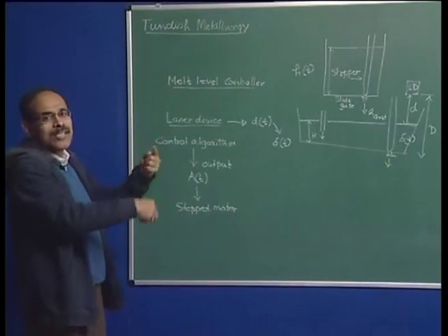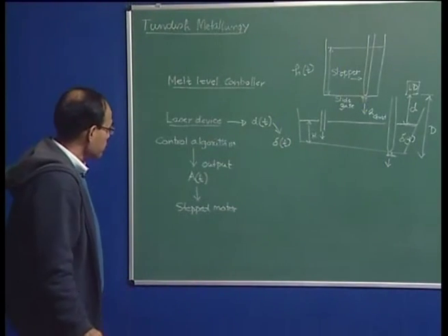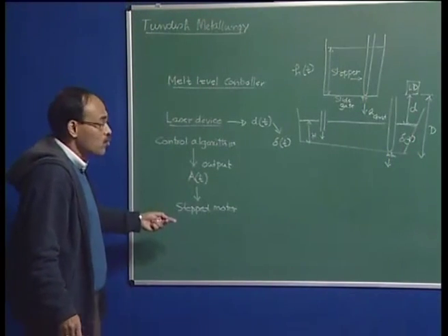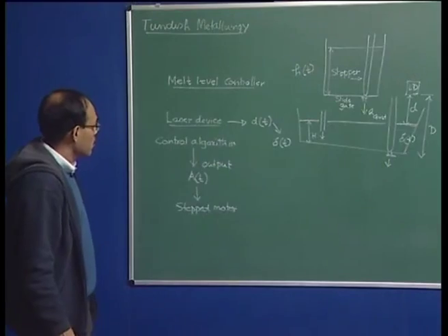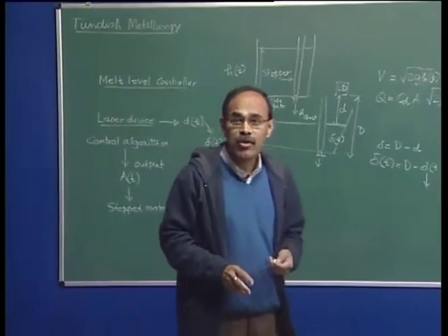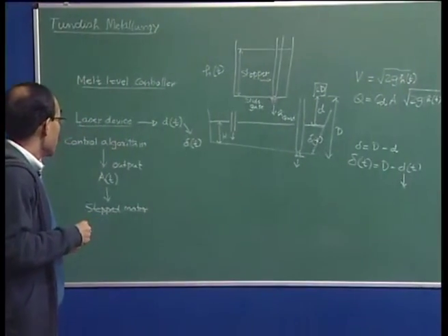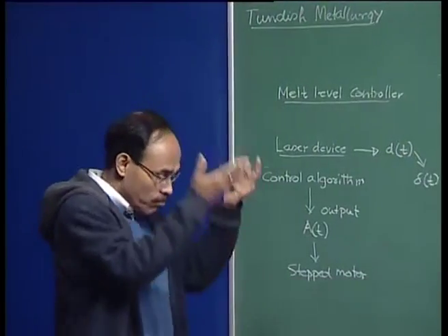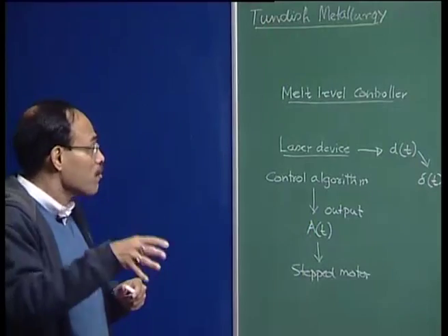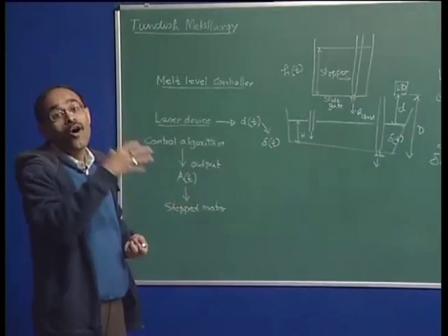So, this type of simple process control in the steel making shop, which we will call dynamic control of the tundish bath depth, is a very simple control algorithm and melt level control procedure that I have illustrated, but there are much more sophisticated control algorithms available in the BOF shop and the continuous casting house, where the fluctuation of the mold or the decarburization rate in oxygen steel making converters is being controlled, and everywhere we will see that extensive process control is being applied either in an offline fashion or in an online fashion.